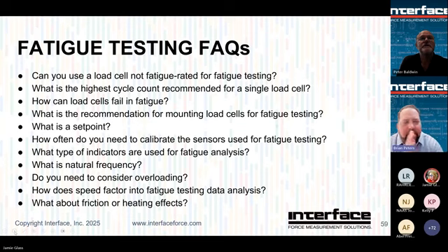All right, what is a set point? Well, set point could be either software or it could be relay driven. Many of our panel meters will have set point options where you can set a particular force value to where it'll then trigger a relay on the back. And that relay can then go and maybe signal an alarm. It can signal a light. It can maybe shut off a hydraulic actuator, shut down the test. So you don't need full-blown DAQ necessarily to be able to set up a fatigue test stand. So set points are good to understand, and we certainly can help with different options depending on what you're looking to test with.